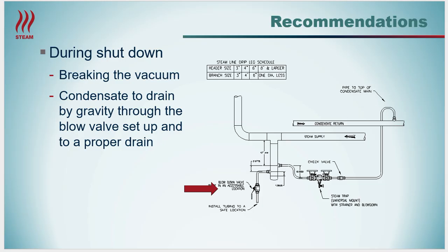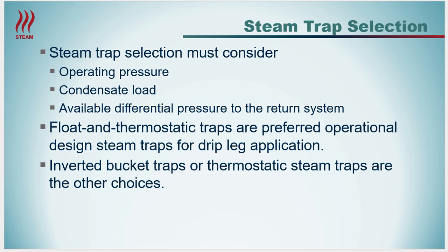Steam trap selection must be considered at operating pressure, condensate load, and available differential pressure to the return system. Float and thermostatic traps are preferred operational design steam traps for drip leg applications. Inverted bucket or thermostatic steam traps are other choices.